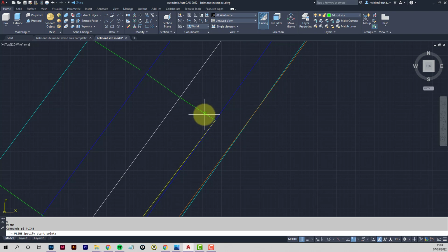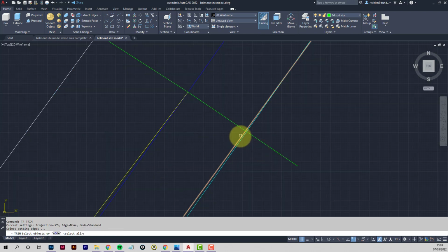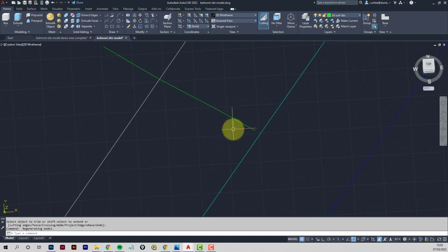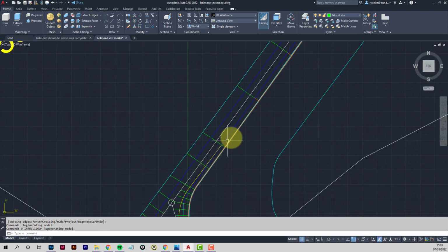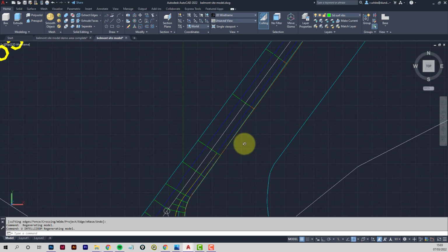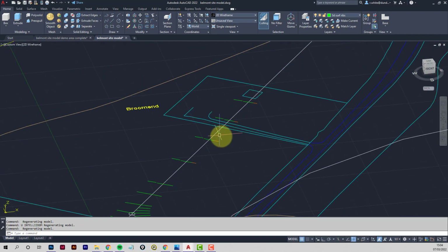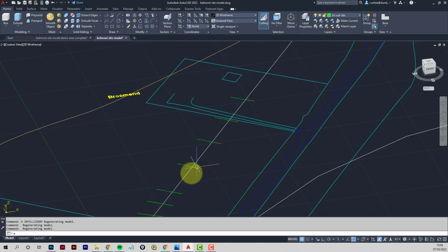So it's a polyline, hover, tab a couple of times, and then bring it out, so that I'm going from my higher up line. That's better. Okay, that's looking okay. We've got ribs all the way along there. You're on the wrong layer. Let's just put those onto the ribs layer.